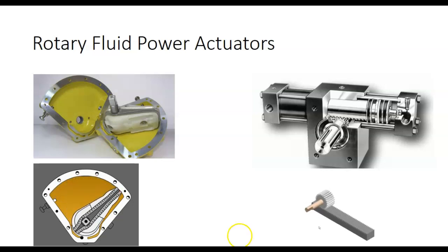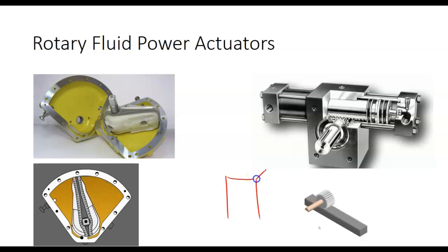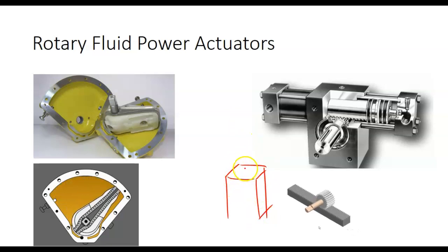We have some that are mounted on the side, and then they have an assembly. When this pushes up, it turns a rack and pinion and turns that into a rotary motion. So this is over there on the buffer station, where it's holding the cylinders while it's waiting for the robot to catch up. It's linear to rotary, so it's got a rack and pinion in it too. We have 3 of those on the Festo line.